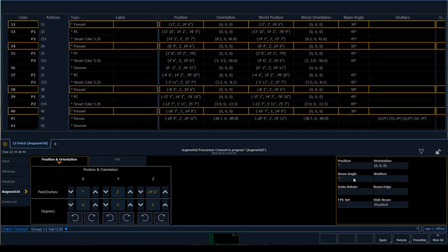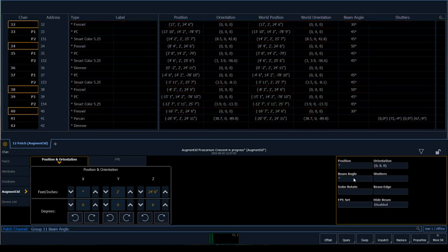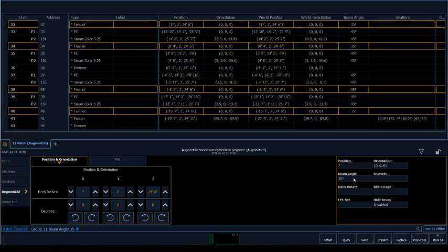These are the things we're going to want to change to suit our fixtures. As I've got 4 selected, they will update all 4 at the same time. So, for example, if these Fresnels are going to be somewhere around the realm of 35 degrees of a beam, I literally can just type that in, hit enter, and that updates.